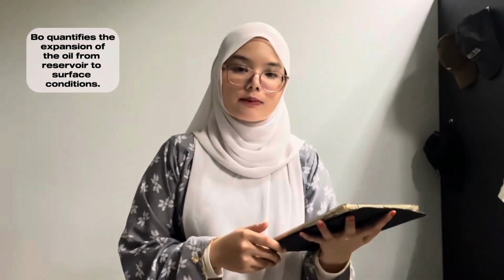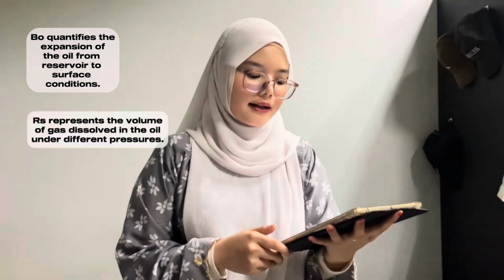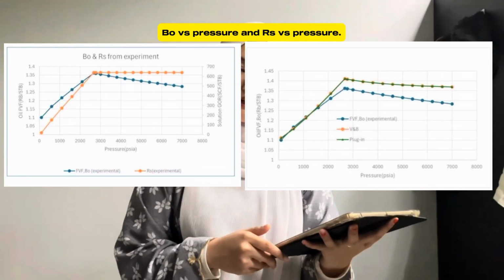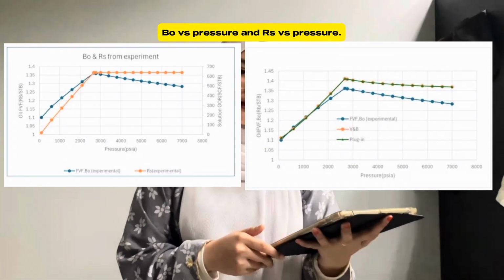Bo quantifies the expansion of oil from the reservoir to surface condition. Rs represents the volume of gas dissolved in the oil under different pressure. With the correlation and Excel add-ins, we plot Bo versus pressure and Rs versus pressure. We compare these two with lab data to validate them.